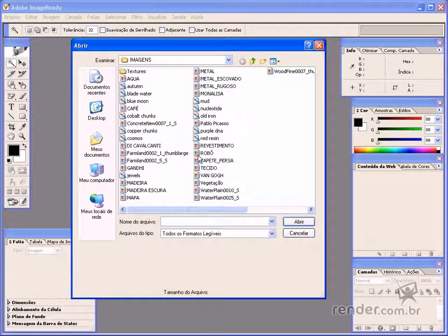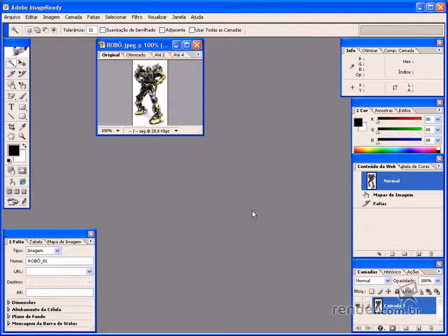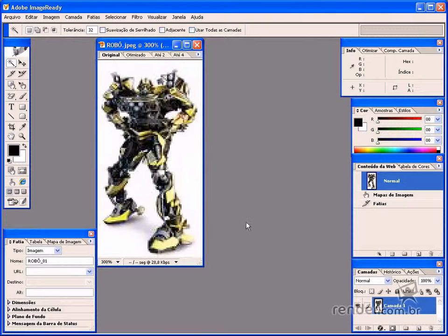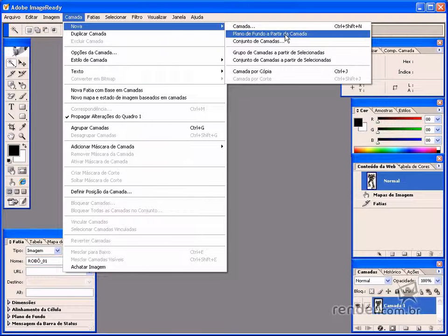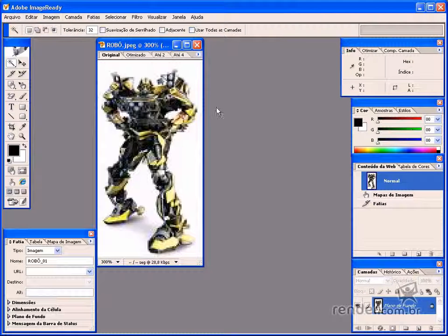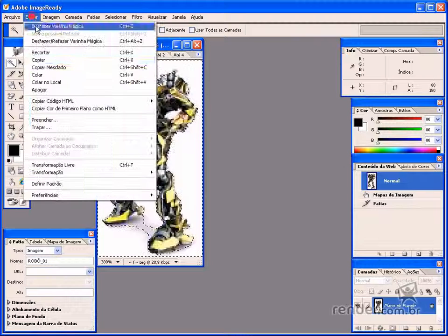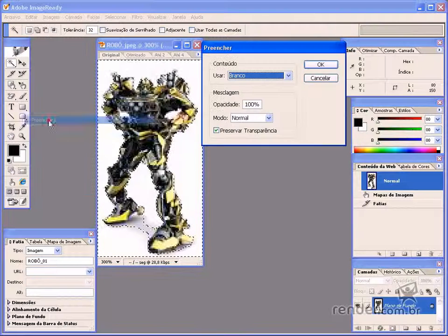Open an image and let's edit the opacity map. We recommend using a high-resolution image as this will exert an effect on the final rendering results. Enable the background layer option and use the magic wand tool to select the area around the picture. Use the magic wand tool very carefully so that the mask is correctly selected, so that no unwanted parts are displayed.